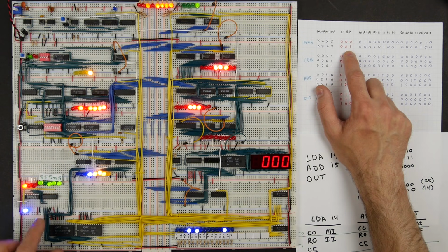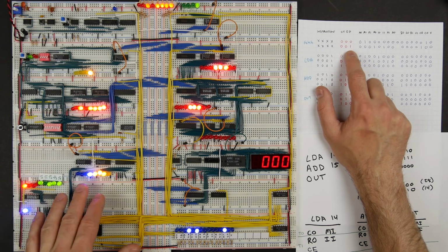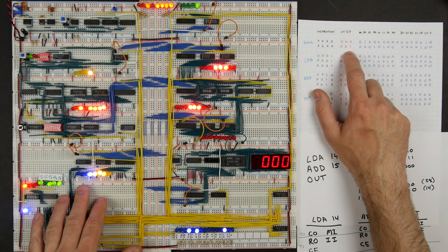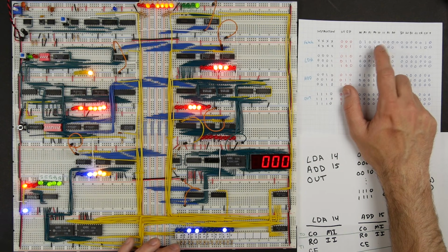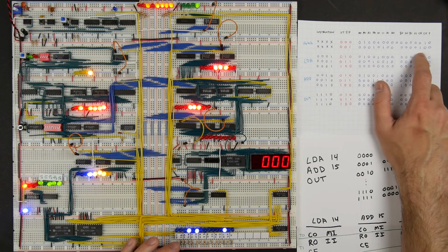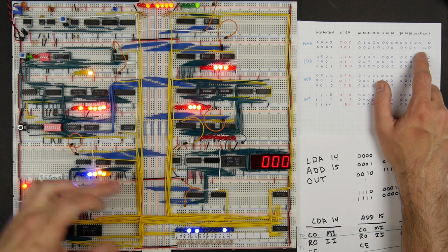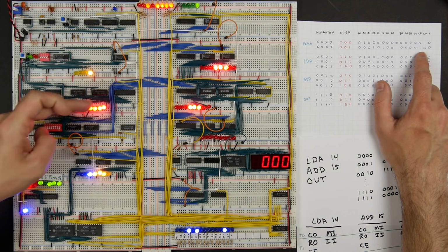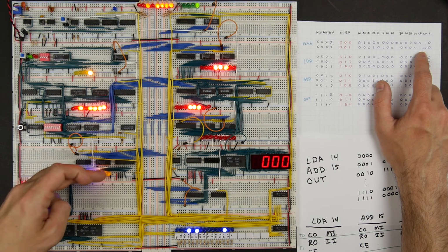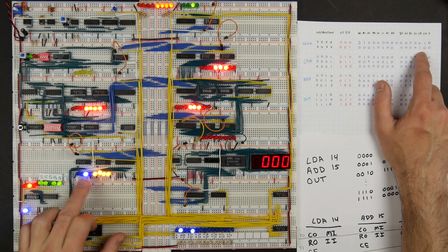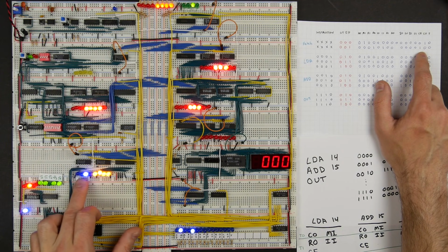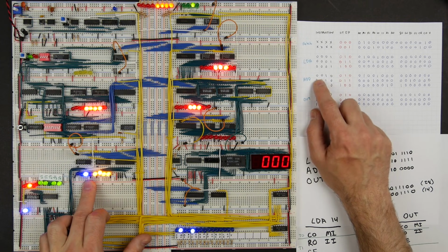And so now we're at time 1, T1, so 001. And again, it doesn't matter what our instruction is, we're still going to do this RAM out, instruction register in, and counter enable. And so that's what we have here. So we've got our EEPROMs programmed correctly. And so we'll see the RAM out, so we'll see this contents here move into the instruction register, and then also the counter incremented here. So now our instruction register, we've got 0010, and that's the opcode for add.